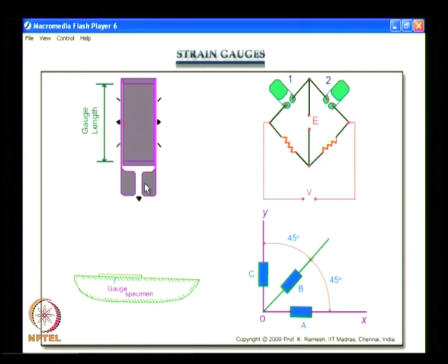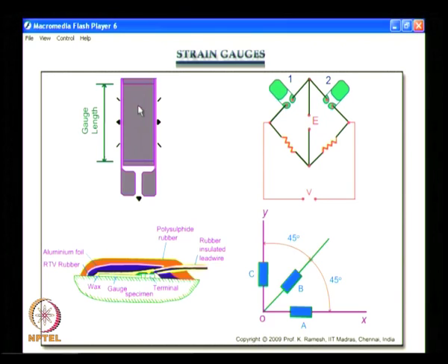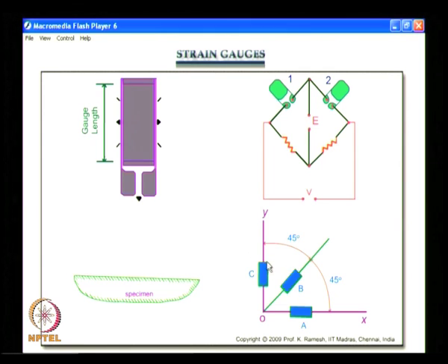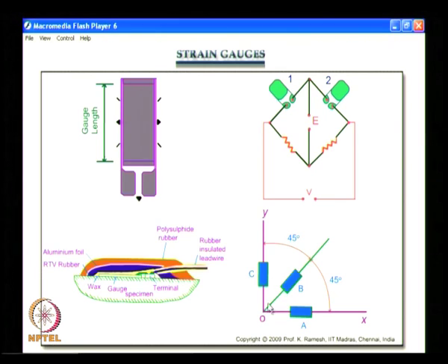And I have also always mentioned that a strain gauge gives the component of strain along its gauge length. Suppose I have to find out strain at a point, then I need 3 strain gauges, and here it is shown as a rectangular rosette. And you also make an approximation that you paste strain gauges here, but it measures the strain at the point O. So, there are engineering approximations in the methodology of strain gauges that you will have to appreciate.